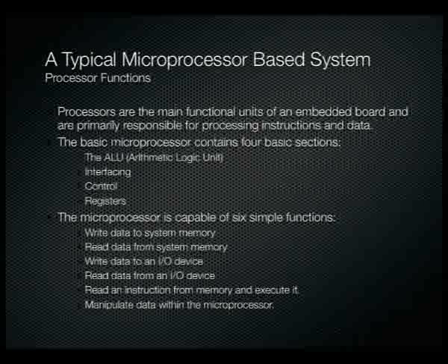We also have a control section inside the processor. The control section is solely responsible for ensuring that our instructions come through into the core at the appropriate times. The instructions are then decoded, and the various functional blocks, the various components of the ALU, are turned on at the right time to ensure that the instruction can be implemented correctly. The last component we normally have inside a processor is, of course, our registers. This is our register set, and basically consists of some internal memory where we can store variables and data while we manipulate them inside the processor core, but more on registers later.